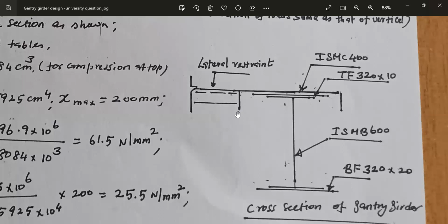They want to get increment, they want to get PhD degree, and they will include it, they will push it into the code also. It is meaningless to consider the effect of torsional buckling, lateral buckling by using all those equations. We have to provide the lateral restraint. That is the job of an engineer. You have to provide the lateral restraint. You have to make it laterally rigid. Then full stress is allowed.